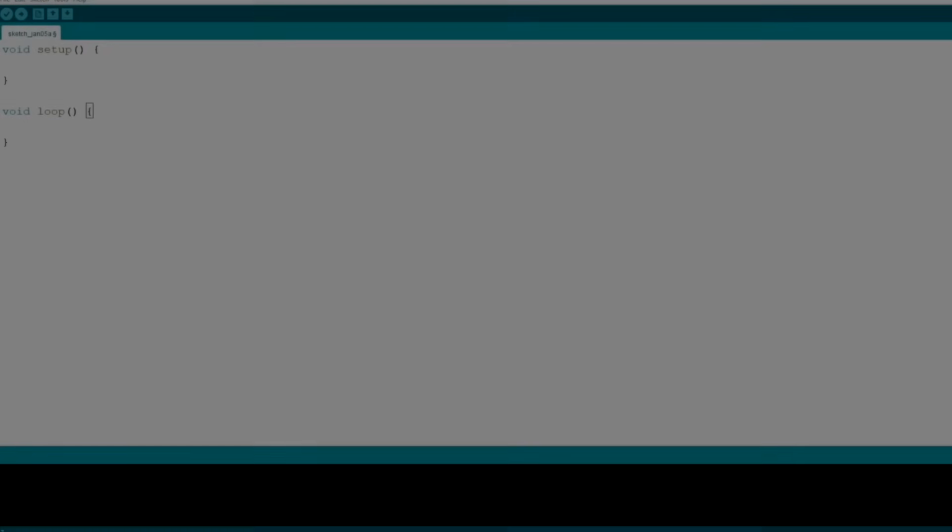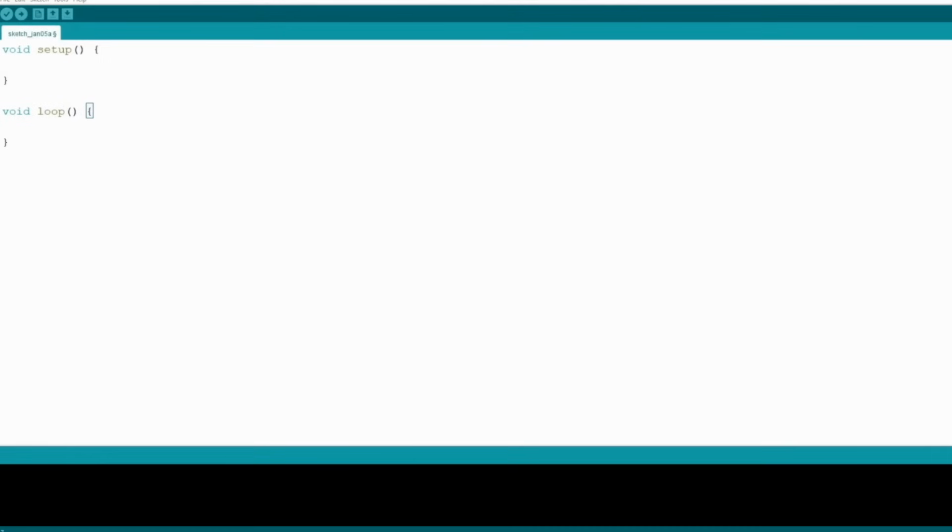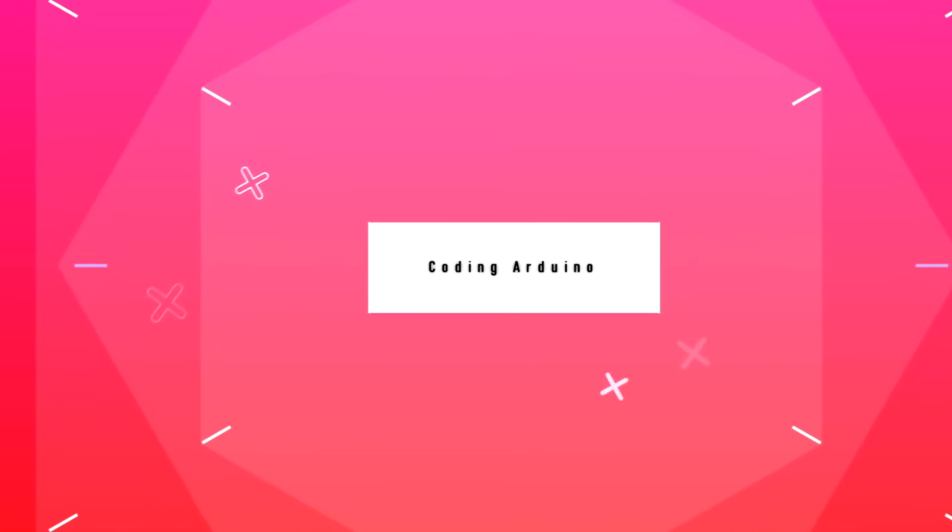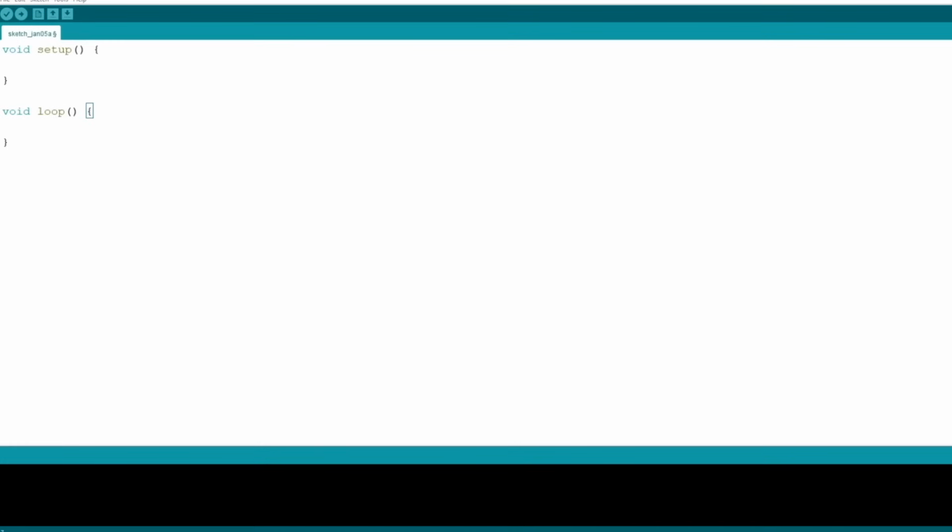Yes, my dear friend, in this lesson we will write our Arduino codes. First, let's include our LCD Display Library. So let's move to the top and include our LiquidCrystal_I2C.h, and also move to a new line and define our LCD screen.